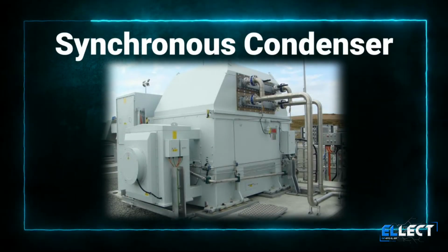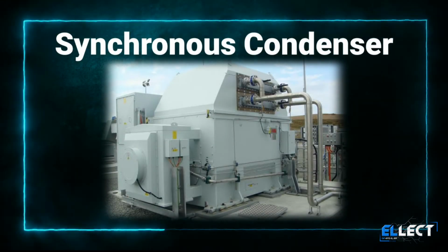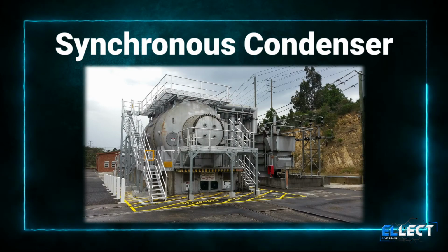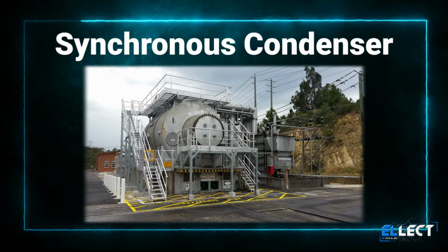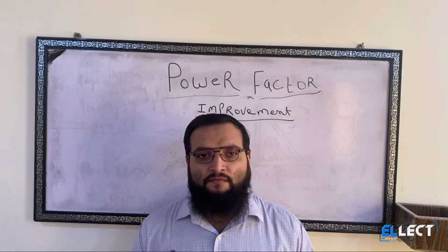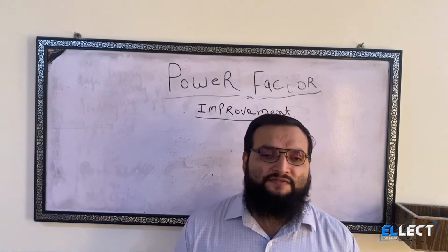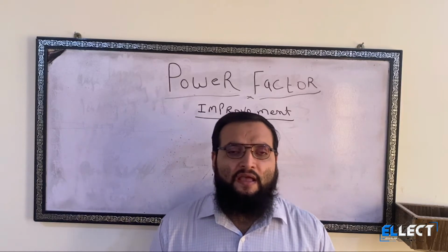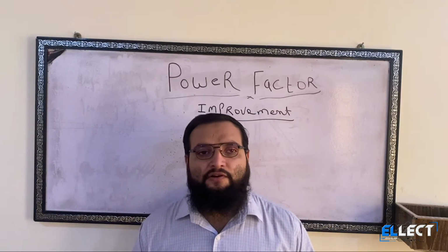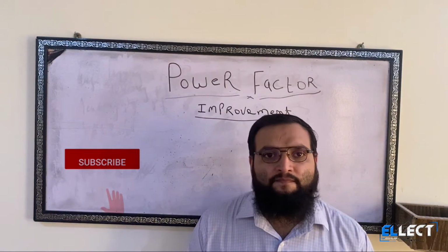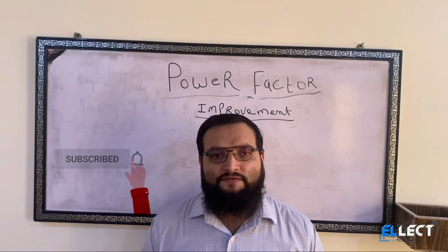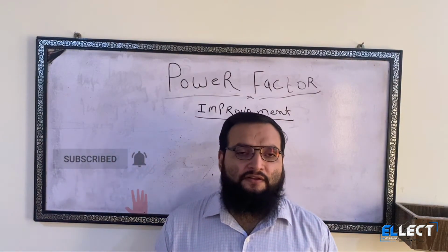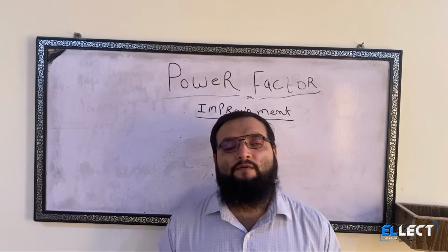And a synchronous motor is installed at large industries to improve the power factor, because whenever the synchronous motor is running on no load or overexcited, it works as a capacitor because it draws the leading component, and that leading component of the current will neutralize the lagging component of the current. So there are many advantages and disadvantages of this method over the other methods of power factor improvement.